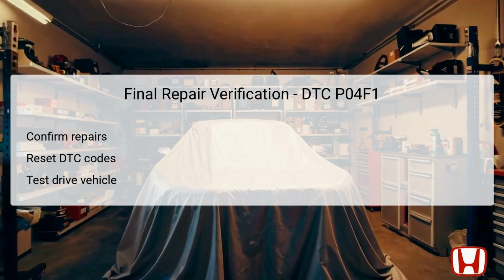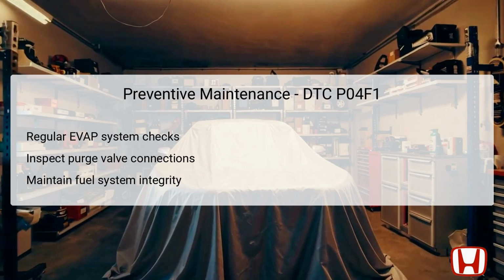Preventive maintenance plays a vital role in ensuring the longevity and proper functionality of the EVAP system. Regular checks of the entire system can help catch potential issues before they escalate into major failures. Inspecting connections to the EVAP canister purge valve is essential, as any loose or corroded connections may affect its operation.